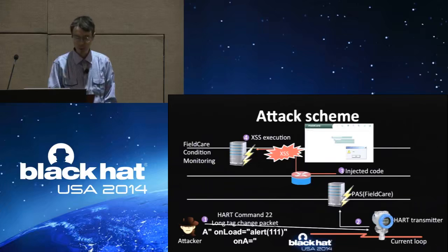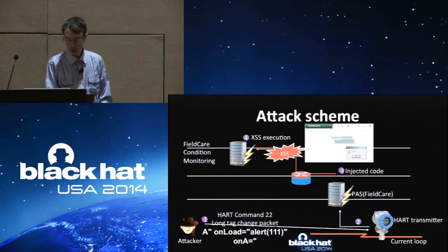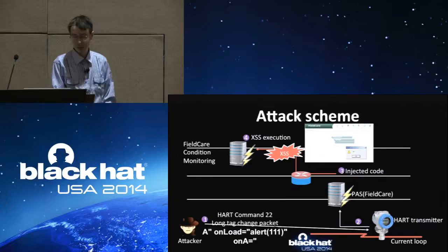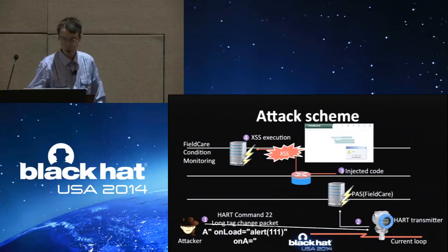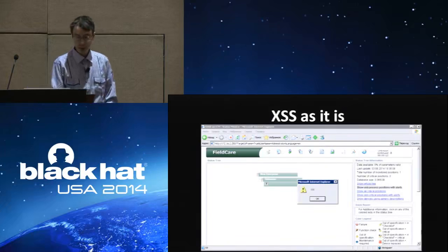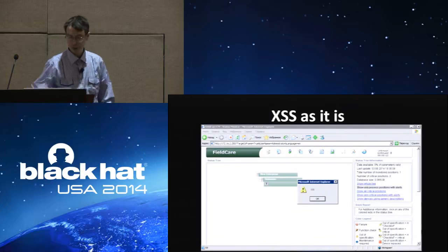That's because FieldCare supports long tag length up to 200 bytes and breaks the HART standard, and real HART transmitters don't suspect such a bug or such a feature. And here we have our XSS through analog industrial protocols.